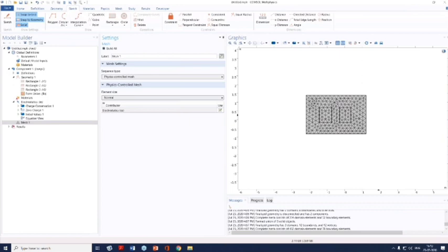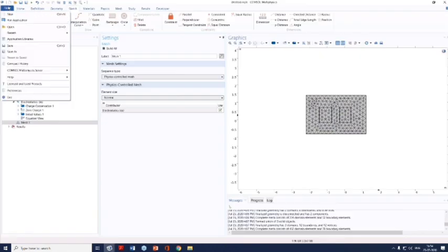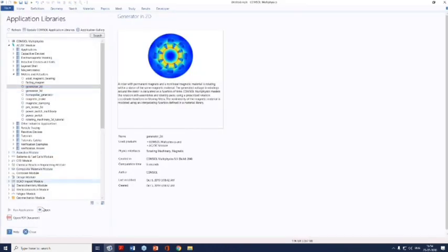What is the difference between the cumulative selection and the identity pair? Well, the usage itself is quite different. The identity pair will get created when you are using form assembly. And as I was mentioning, when you are using form assembly, the same set of boundaries will have different identification from two different domains. So, for example, as we were discussing earlier, maybe I will just open that generator model again. With that, it will be quite easy to explain.